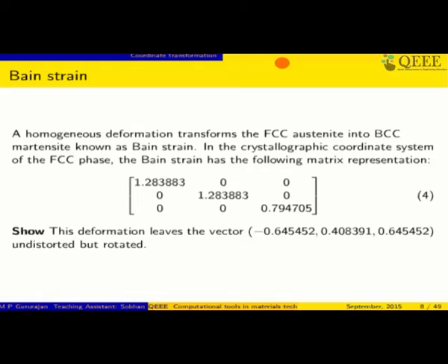When you quench it very fast, it doesn't undergo the usual phase transformations that it would undergo. Instead, it produces this martensite phase, and this is not even an equilibrium phase. If you have a phase diagram, you will not see martensite there. So this is a non-equilibrium phase that comes about when you cool the material very fast. When you cool the material, it does not have time to change into the other crystal structure that it would prefer to have, which would reduce its free energy. So thermodynamically, that is the most stable state, but for kinetic reasons it's not able to go there. There is no nucleation, there is no growth.